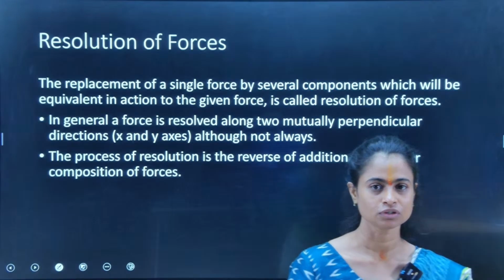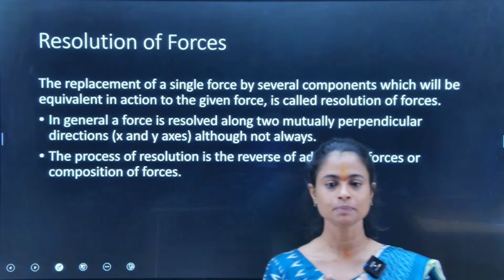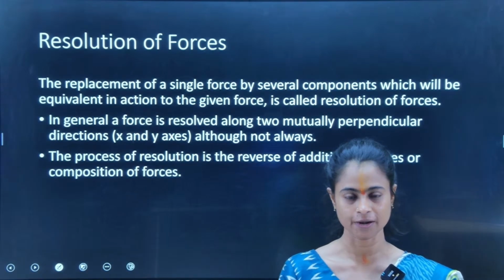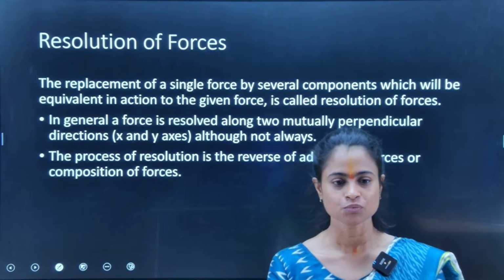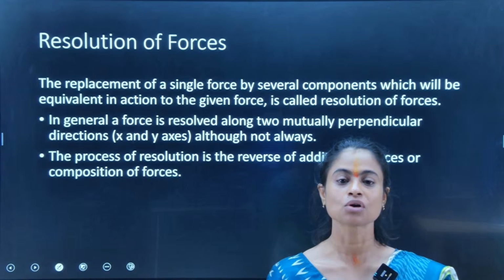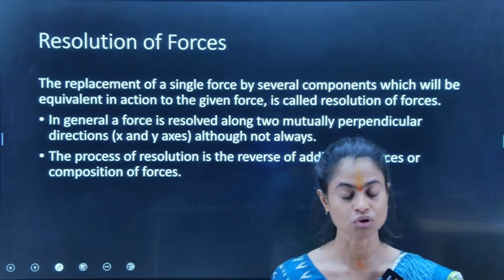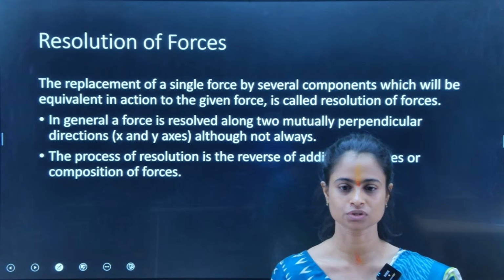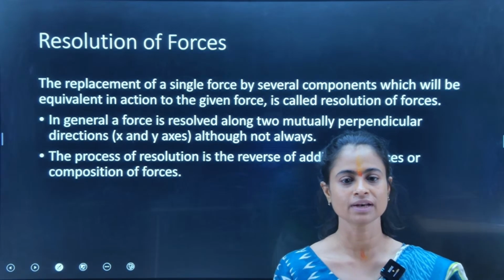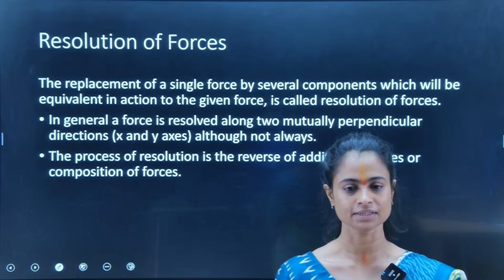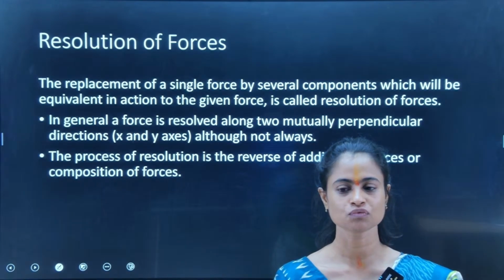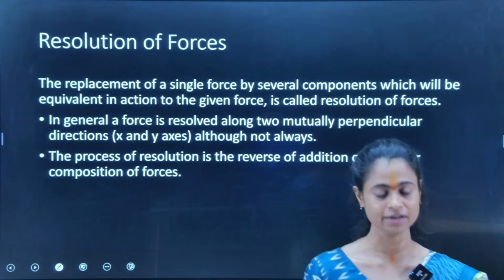So, resolution refers to the process where we split or divide a single force into a number of forces. These forces which are formed from the single force are called the resolved parts of the given force, or the components of the force. These components will be equivalent in action to the single force that is given, and it's exactly the opposite of the composition of forces or the addition of forces, right?